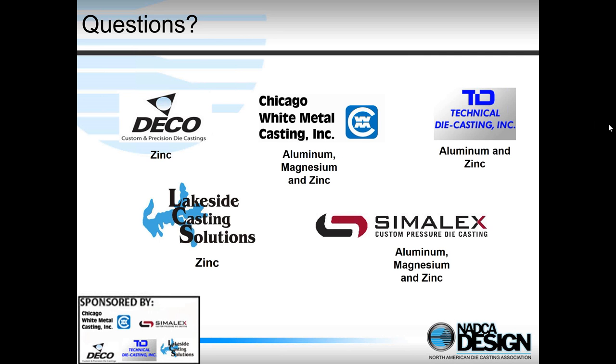Well, generally a thin wall die casting is somewhere 2-3 millimeters. So what's that? 80 to 120 thousandths of an inch. So if you can stay within that kind of range, obviously it depends upon the size of the casting. The bigger it gets, obviously the thicker the wall we need in terms of filling it. So that's not a hard and fast rule.